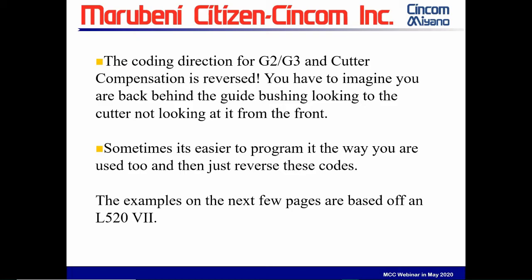For the coding direction for G2 and G3, the cutter compensation is reversed. In other words, what you would normally think is clockwise would actually be counterclockwise. So you have to more or less think of it as if you're behind the guide bushing rather than in front. So if you're making a clockwise move on the shape, you actually have to program it in G3. Now, sometimes it's easier to program the way you're used to and then just reverse the G2s to G3s and the G3s to G2s. And the cutter compensation, G41 or G42, just reverse it.